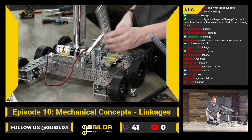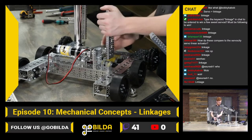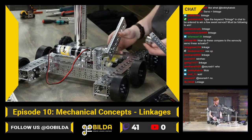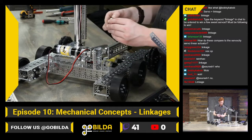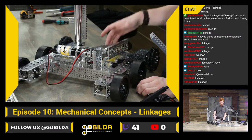And that can make a really smooth movement too, but it may not be quite as good at handling side load as a dual pattern pillow block, because here you've got your thrust bearing. Thrust bearings are really nice at thrust loads where you're applying a lot of load down onto that bearing, where standard radial bearings just don't handle that quite as well.